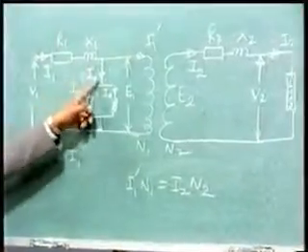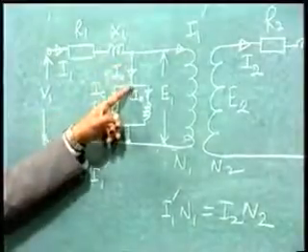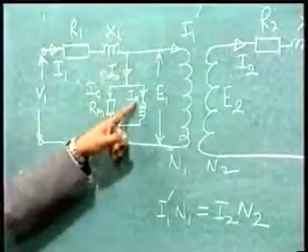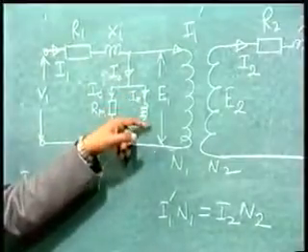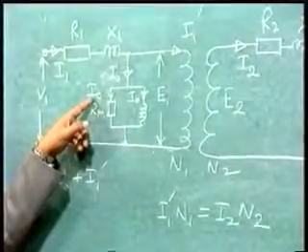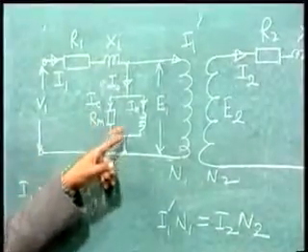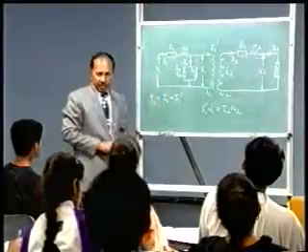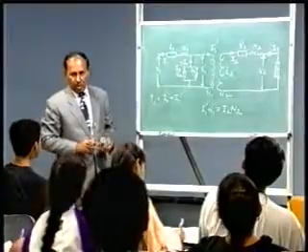So you see I0 has two components, IC plus IM. Here you apply incoming current I0 is equal to outgoing two currents IM plus IC. And IM is the magnetizing current. IM lags the voltage by 90 degrees, so it should be shown flowing through an inductor. And IC is the loss component current, so it should be shown flowing through a resistor. So we have shown RM and XM. These two together are connected here. So this is the complete equivalent circuit of the transformer, for which you had drawn the complete phasor diagram earlier.